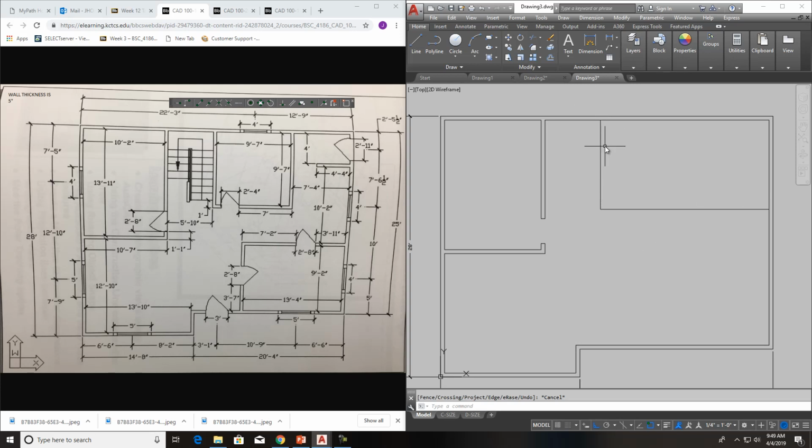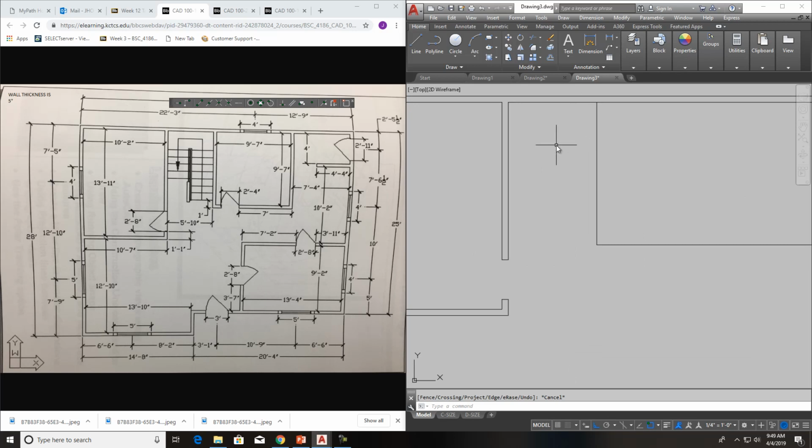But inside here now, when we're getting ready to put these steps, 1 foot back, so I'm going to put me a line. I'm just going to stretch this line across, or actually I'll put another one so I can delete it off. Offset 1 foot, and this is where we're going to start our stairs. Okay, there's 1, 2, 3, 4, 5, 6, 7 treads. Okay, and offset, usually these are 10-inch treads. So 1, 2, 3, 4, 5, 6, 7.